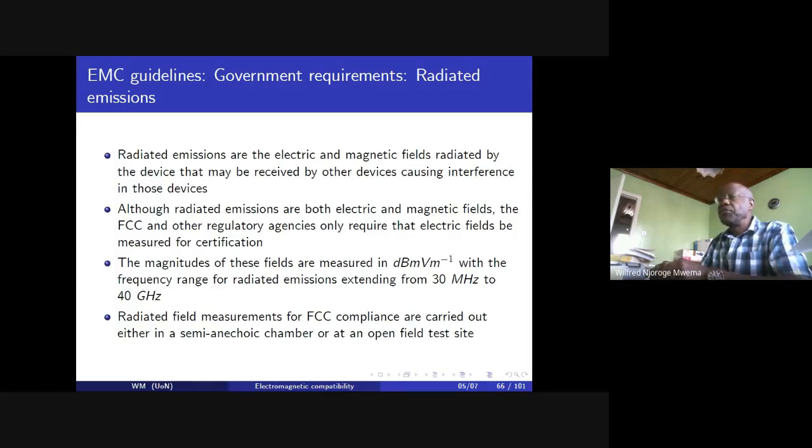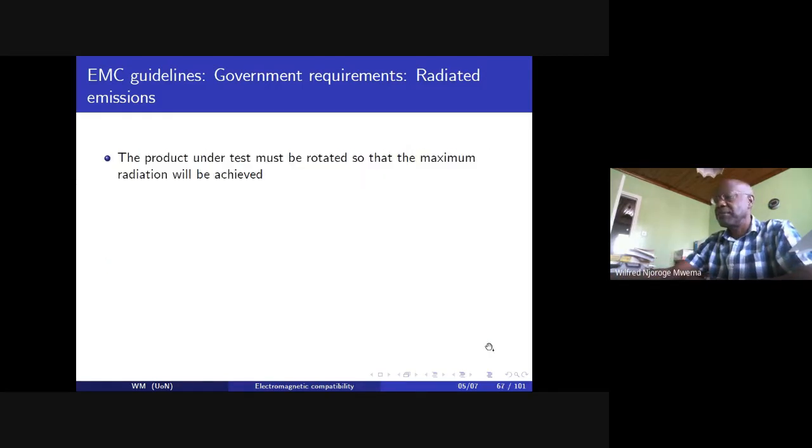If you recall, if you have reflections, we can set our antenna at a node where we have destructive interference, and the fields that we'll be measuring there will be less than the maximum that the system is producing.